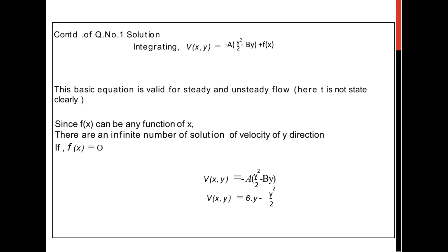That is, the property does not change with respect to time. But in unsteady flow, the property of a fluid particle depends on time. Since in this question time is not given clearly, this equation will be valid for both steady and unsteady flow.